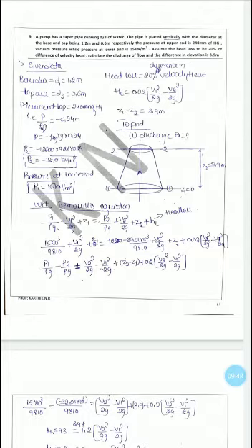Then here we need to convert that pressure, 240 mm of Hg of vacuum pressure. The conversion is P by rho g, which is what the pressure head is. The pressure head P by rho g is equal to 0.24 meter of vacuum pressure. Therefore, since it is a vacuum pressure, we need to write it as minus 0.24 meter.